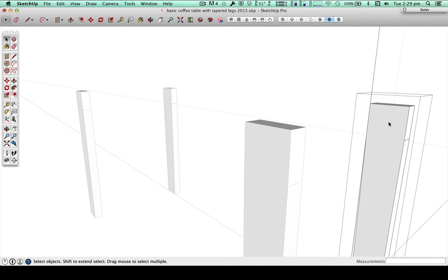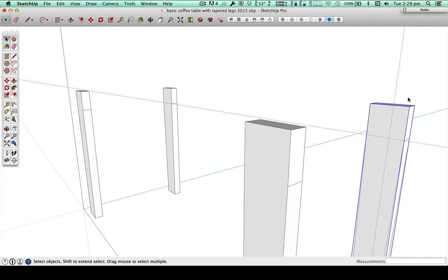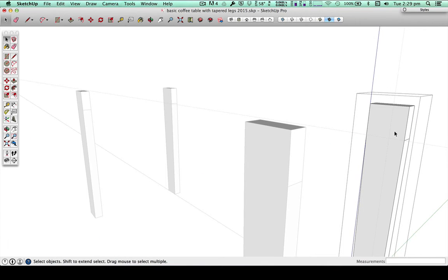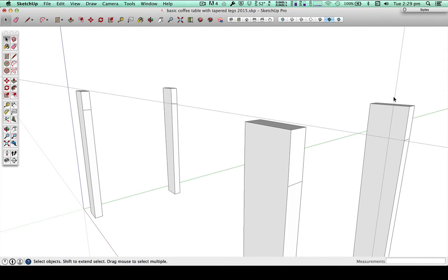And that's really important, because as we start to turn this thing that I make into a 3D object, being a piece of timber, I'm going to group it, and it will be a separate group from this, so I can move it around. Very important to remember that. When I drew these guides, sometimes it matters if you're in edit group mode and then draw the guides, but these guides are actually not connected to this group. So this guide is an independent little guide, and that can be useful.